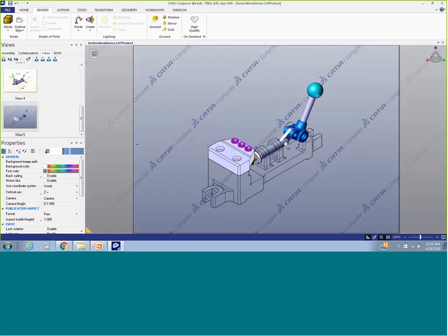I'm going to save that away basically as view number 5. And then also you do have a couple other choices here. You can come back here and change the outline style. So again, I could potentially come over here and say I want sharp edges. I don't want to see them. I do want to see them. And these are different drop-down choices you can easily switch to as well. So I'll leave it here at the construction edges, which is the default.